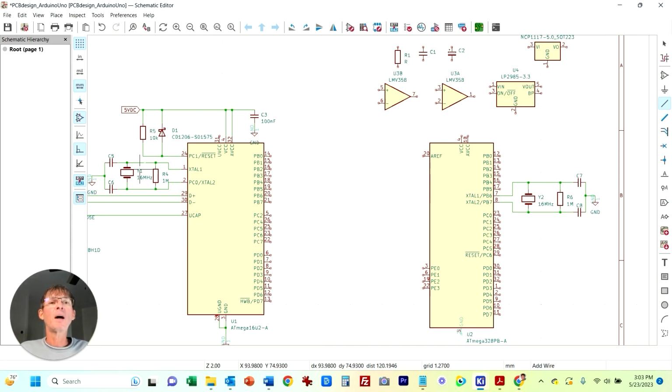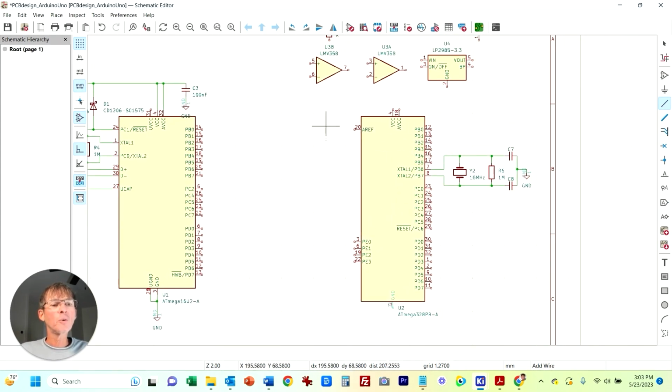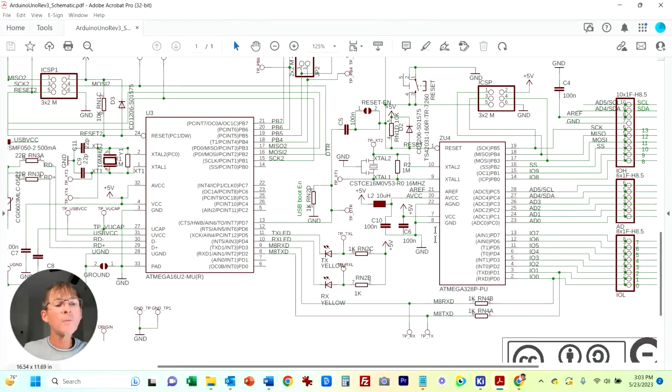And then anything with high power you need to be careful with as well. Okay, so we've got that. We've got our crystal. Let's look at our power supply for this one. We have the VCC line. So we have our VCC goes to 100 nanofarad. Then we have AVCC goes also to 100 nanofarad to ground.